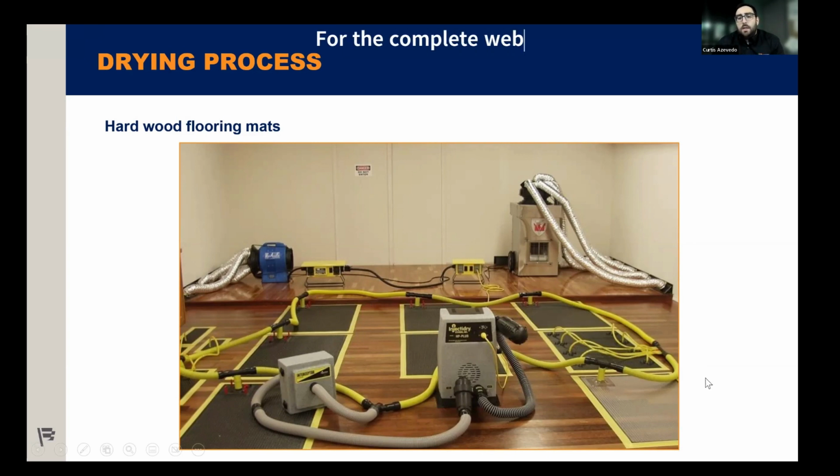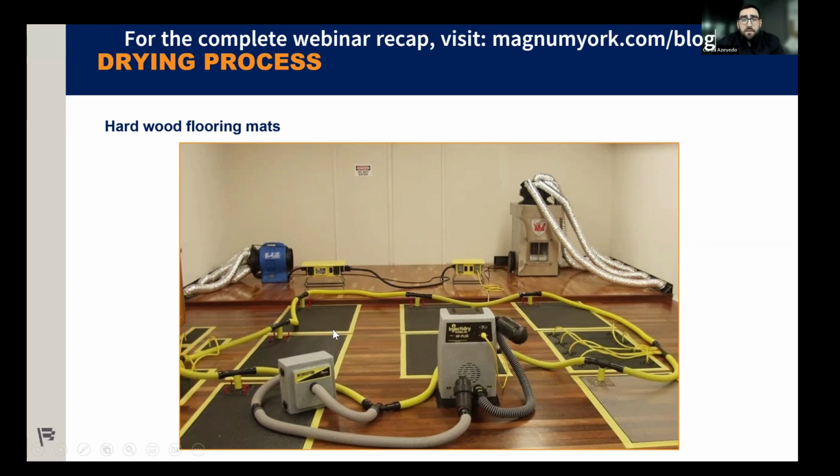So when you have a very limited amount of surface space that you're trying to dry, and access essentially drying a subfloor throughout this entire area without removing the materials, setting up some equipment like this can have a major impact on the potential of drying that space.